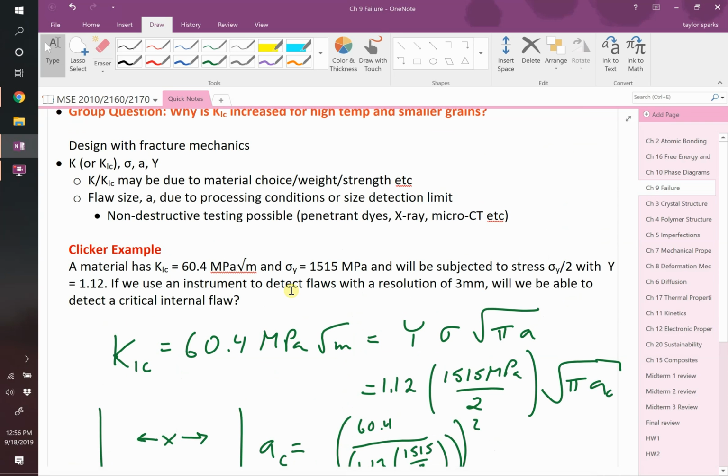You could look it up on that spec sheet and say, okay, if that's my fracture toughness and I want to avoid fracture, then I've got a couple options. If I can't control the stress that it's going to be under, right, if you know that no matter what you do, it's still going to see at most 300 megapascals, then you can design for what the minimum flaw should be in order for this thing to be used safely. And then you could actually test for that thing.